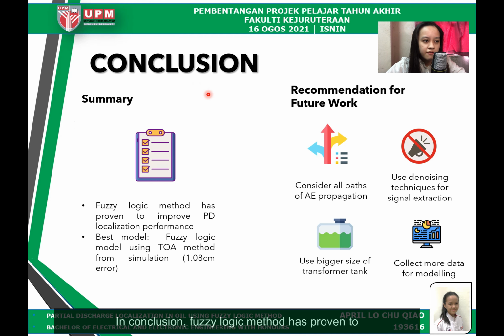In conclusion, the fuzzy logic method has proven to improve PD localization performance in oil. The best model is the fuzzy logic model using the TOA method with only 1.08 cm error. For future researchers, they can consider all paths of acoustic emission propagation, use denoising techniques for signal extraction, use a bigger size of transformer tank, and collect more data for the modeling of fuzzy logic.